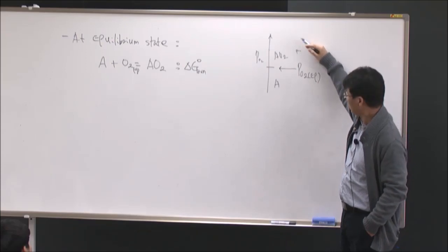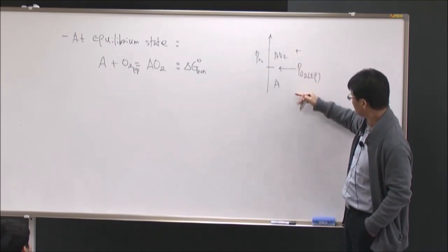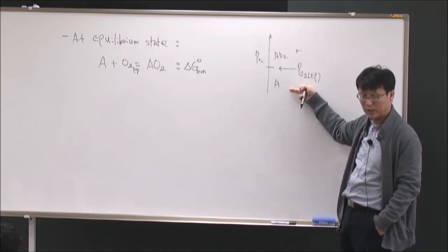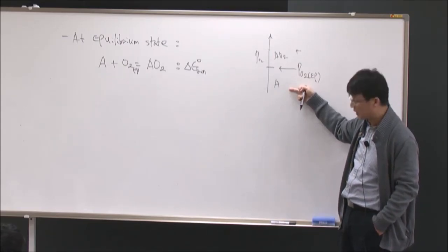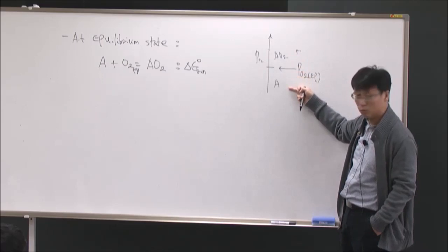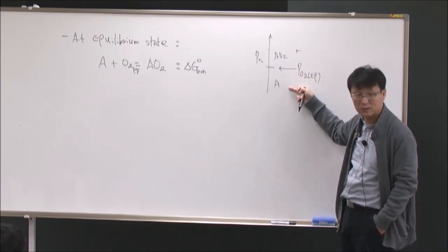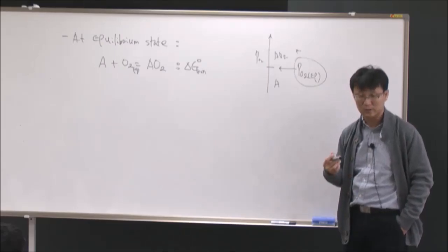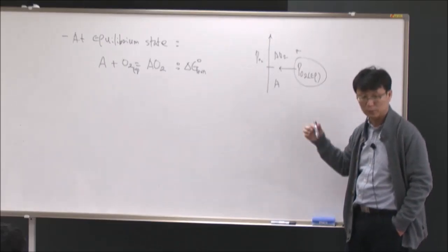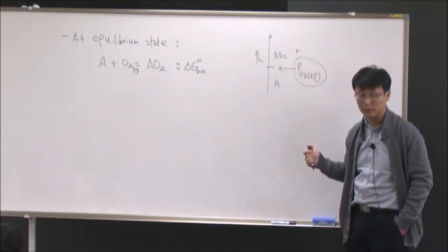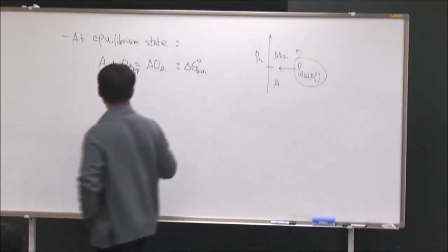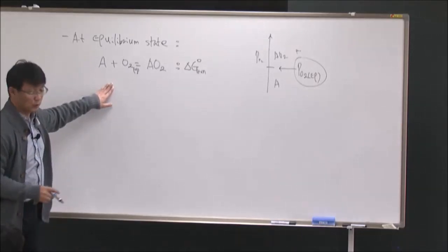And if I put the A oxide into a partial pressure which is lower than the equilibrium partial pressure for the A and A oxide reaction, then my A oxide will reduce back to the A metal. So this value is very important industrially. Very important for many, many different kinds of industrial application.